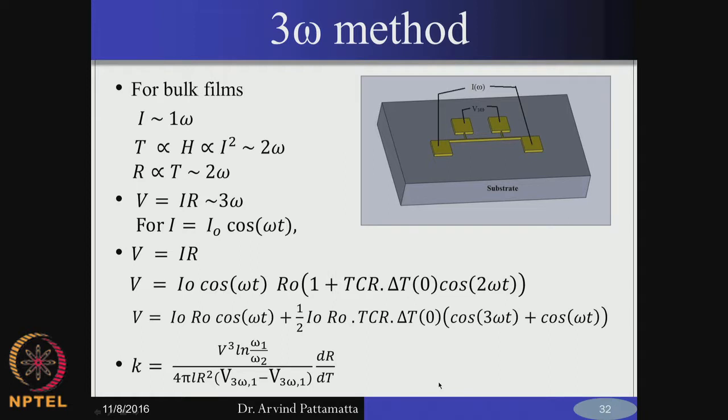That means you have to carry the sample to a MEMS lab where they have the photolithography machine. You prepare a mask, then etch, and then deposit some gold film. Finally you will get what is called a 4-point probe.